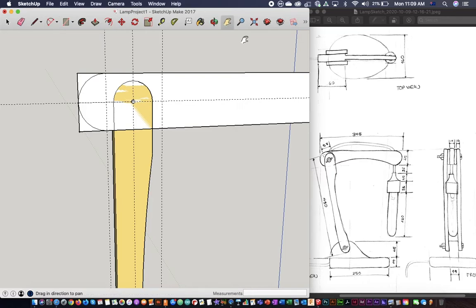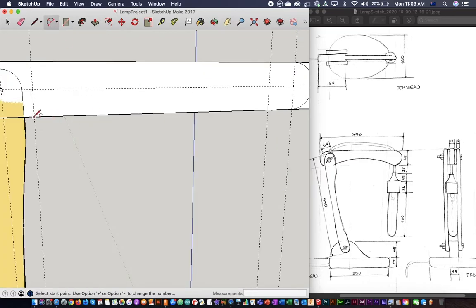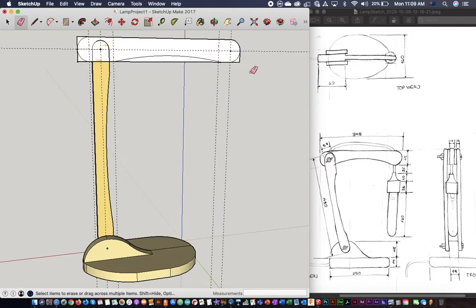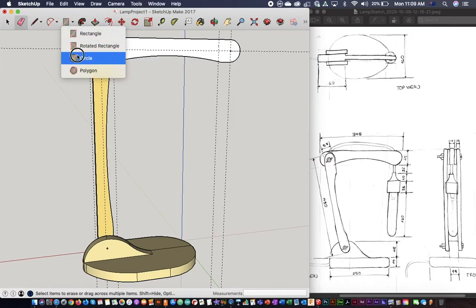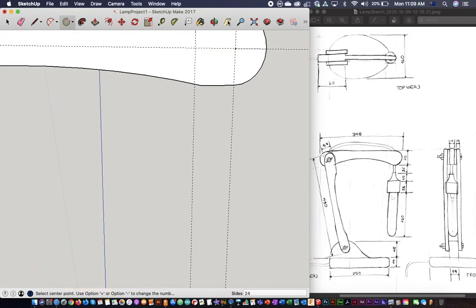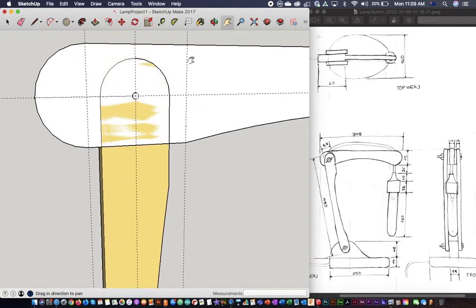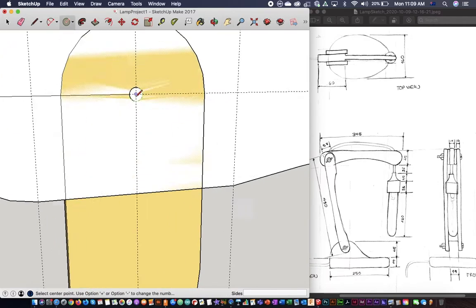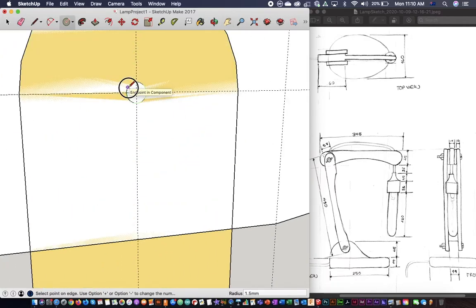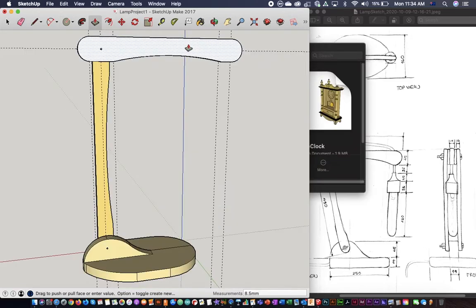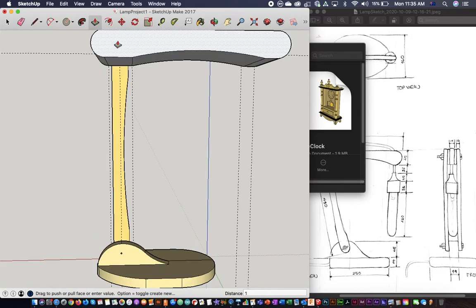Then we're going to do the curve feature for the midsection. I'm going to click on that intersection. We're just going to go up 12. Yes. To delete the bits that we don't need, using the eraser, draw the perforation for this one. Is going to be only on this side. So we already have a reference point, so it's easier to do. And we're ready to extrude the face, and then this is going to be 19.